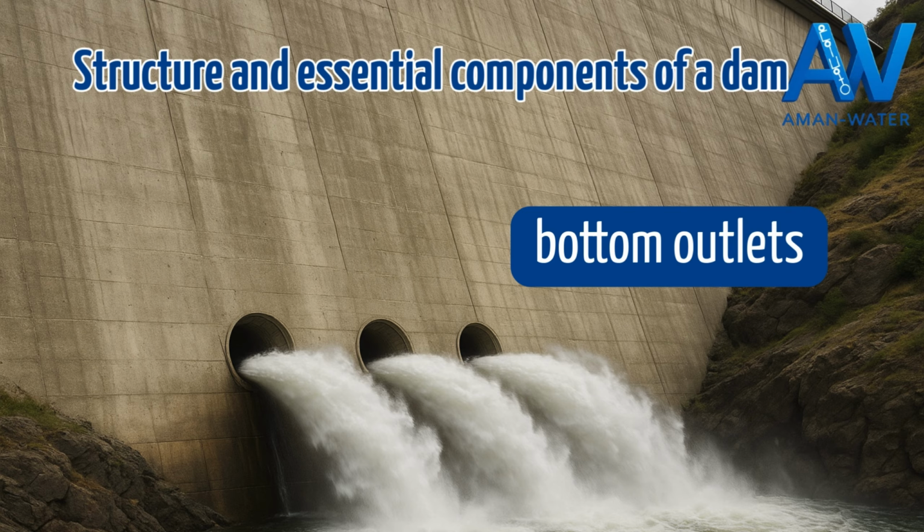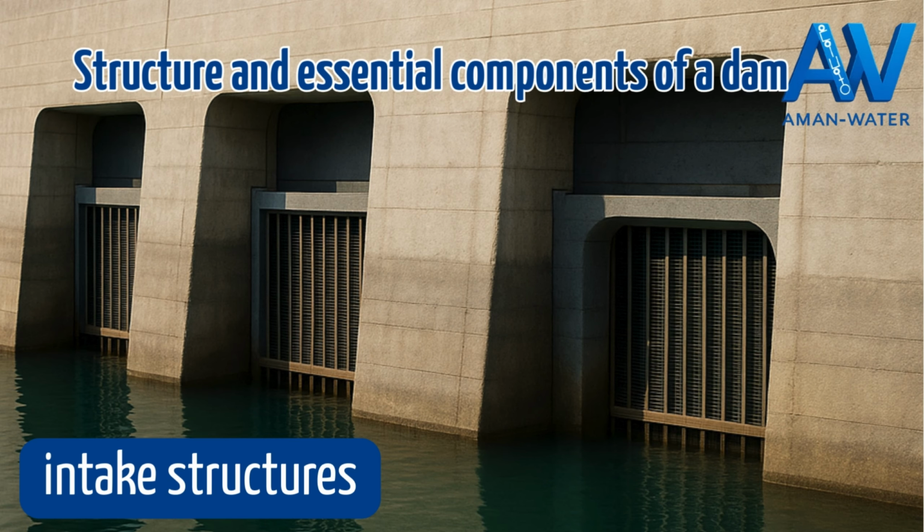Next come the bottom outlets. These are conduits located at the base of the dam capable of releasing a large amount of water. They are used to lower the reservoir level, manage sediments, or secure the dam in emergencies. They are essential elements for keeping control even in extreme conditions. Higher up are the intake structures. These are the passages that supply turbines, irrigation networks, or drinking water treatment plants. Their position depends on water quality and the required flow. With gates and penstocks, the flow can be adjusted precisely.